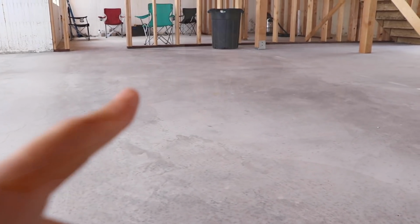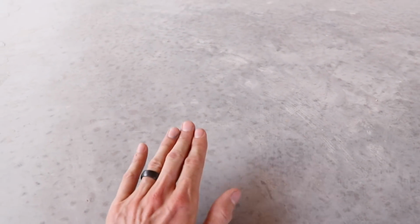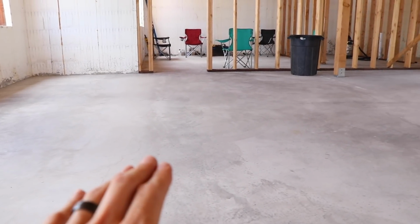And then if you remember from when we poured this slab, there's also 2.5 inches of insulation under this 4-inch concrete slab. So that keeps this concrete slab isolated from the ground below. So as we get that sunlight hitting this, it's going to heat up the concrete slab, and then basically as the sun goes down, that heat will be released back into the house. So just a couple of simple ideas like that can make a significant difference in terms of how comfortable your home is and how much energy it takes to heat and to cool it.